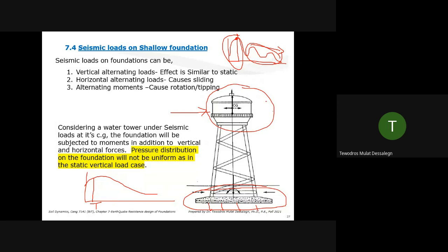That's acceptable in conventional design if you're doing a quick pseudostatic analysis, like a hand calculation. What we did there is we came up with the acceleration, multiplied by 1.5, and so we know the acceleration acting at the top. Then we use that weight and acceleration. Because of horizontal force, mass times acceleration, using that we came up with bending moments and shear force at the bottom. It's good. It's quick. It's conservative.